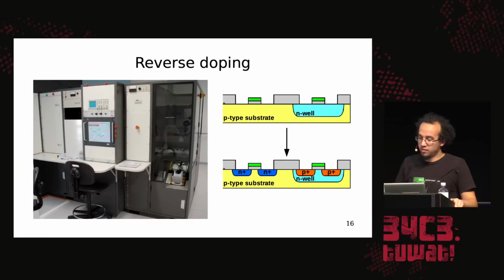You also have here the situation that you don't need photolithography to define the regions which are doped, but you just use the oxide, which is already there, and also the gates. And so everywhere where you have a naked substrate showing, you change the doping by implanting ions.